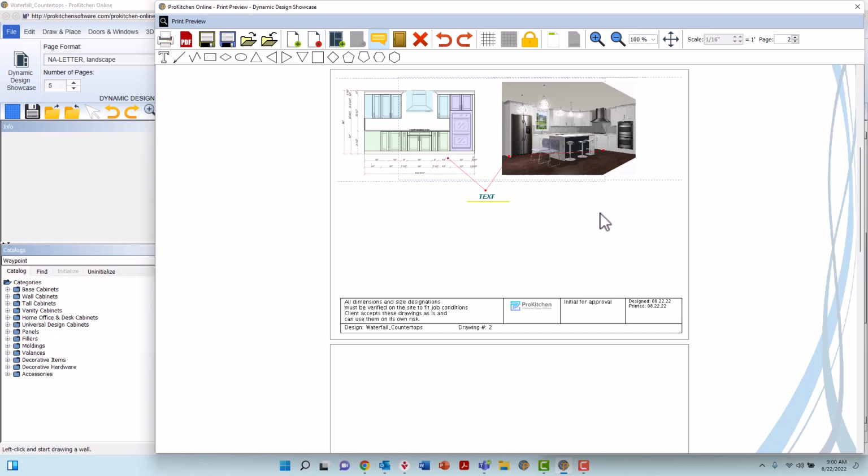The series of shapes are the Shape Comment tools and work just a little differently. Once grabbed and dropped, only the shape will be placed on the page. You may increase or diminish the size by left-clicking and holding any of the points on the outline of the shape.